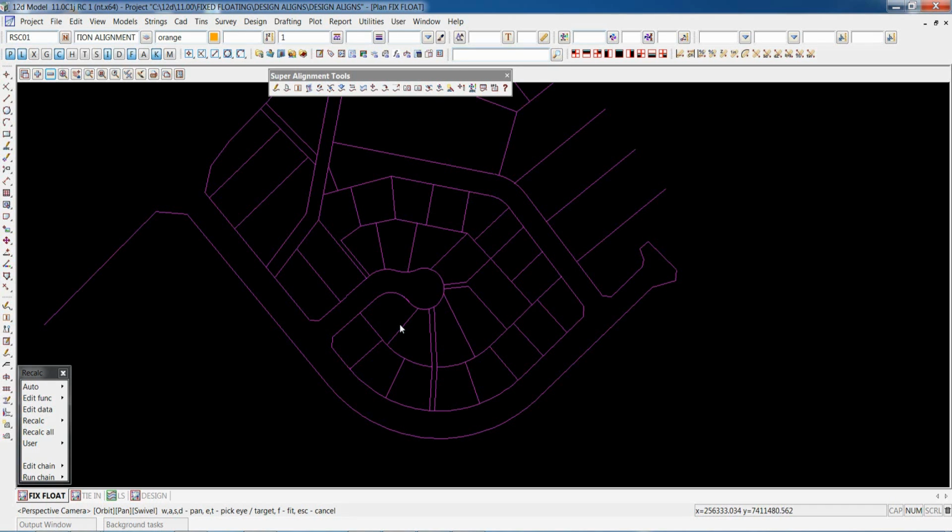Free parts are positioned between 2 solved parts, whether they are lines or arcs, and are solely dependent on those 2 parts in order to solve. So a free arc can be defined by a user-defined radius. And when we go through this process, you'll notice that our signs for radiuses are important. Clockwise is positive, anti-clockwise is negative.